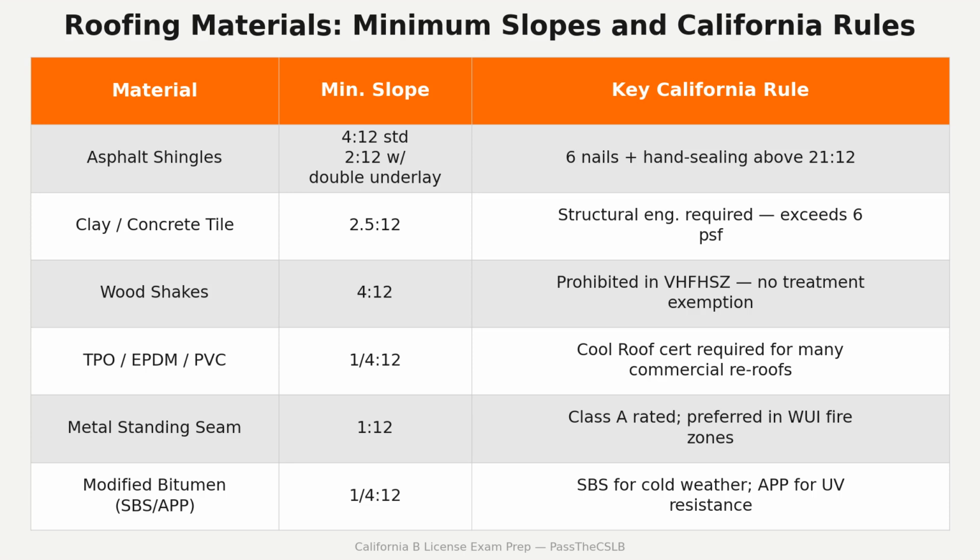They prevent the rafters from being pulled apart at the ridge by wind uplift. Wind pushing upward under the eaves applies a prying force at the ridge. Collar ties hold the opposing rafters together at that joint. Different elevation, different force, different function. Low ties, walls, high stops, pull. Say it once and it is yours.